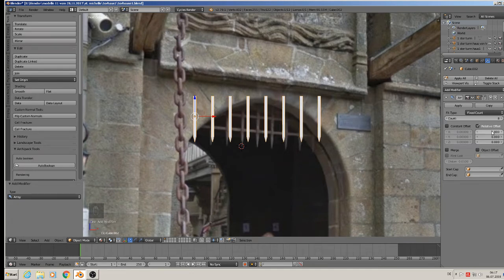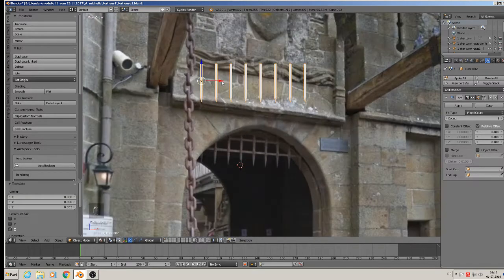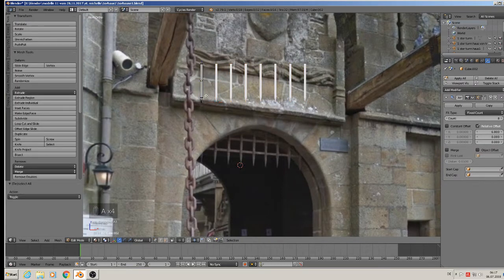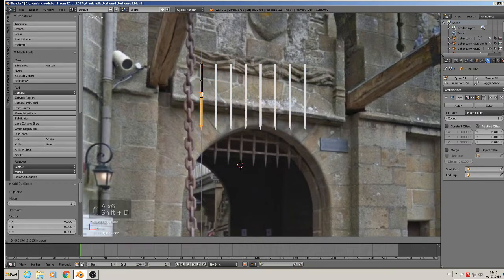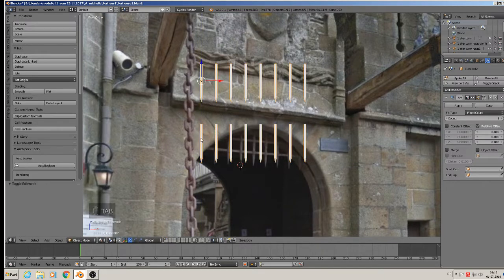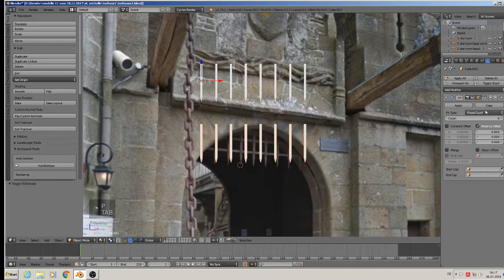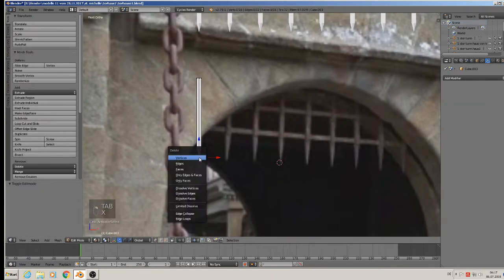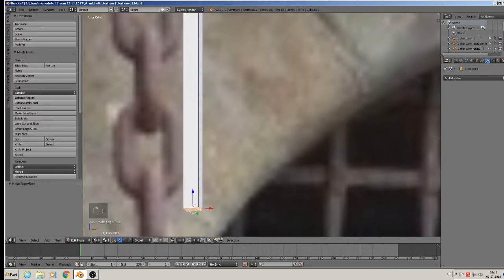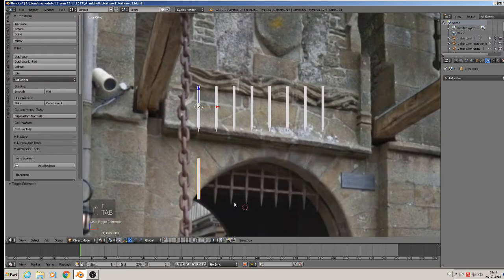Then we have it. That should be that. Now we take that one here, Shift D, and P to separate the selection. Then we can take here this away and this away and dissolve this long axis there. So X, dissolve edges, then it's good. F to close that. Now we have that one.